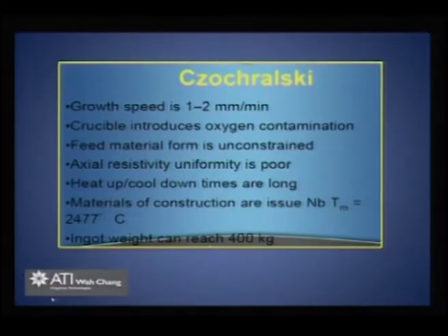And the other parameter in Czochralski synthesis is the growth speed. Typically, you would not see the rotator moving because it is making a very slow RPM. To the naked eye you would not even see anything moving, because you are going through 1 to 2 millimeters per minute. Therefore, it is a very slow process, and it might take even days to grow almost a half a foot long crystal.